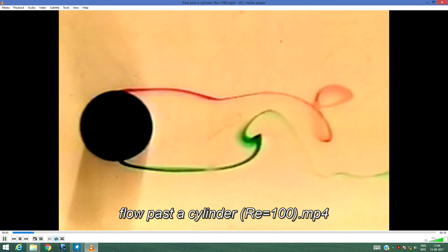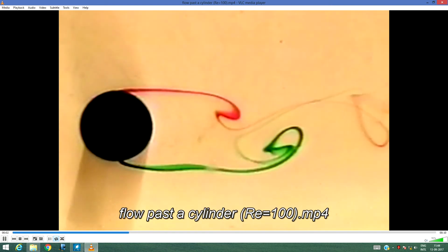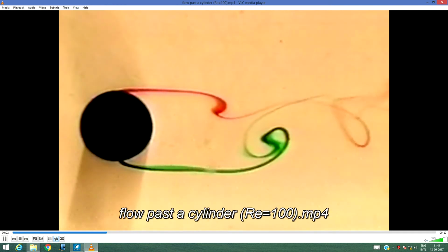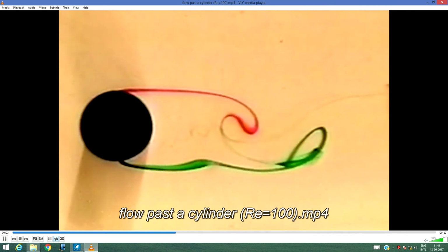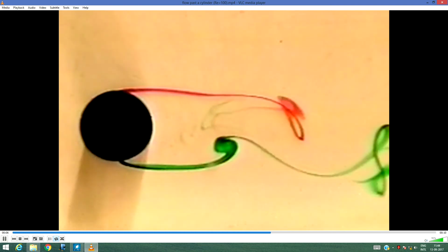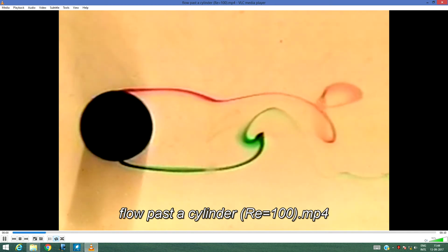Now, what will happen at very high Reynolds number? We saw a sudden dip in the drag coefficient. That point we will discuss later. But right now, I just wanted to compare low and high speeds, and you see that the local details are very different. There is no way you can bring in this information in a global analysis of the flow phenomena. So, that is the motivation behind going into a local description of the flow field.